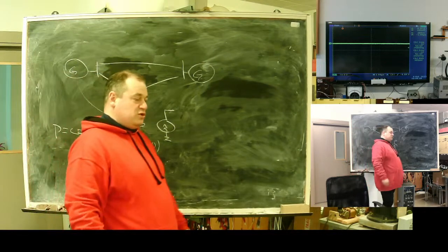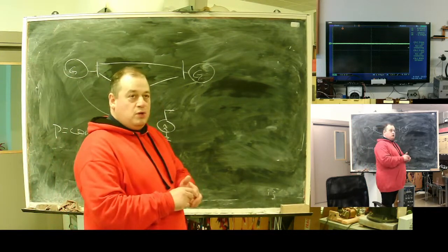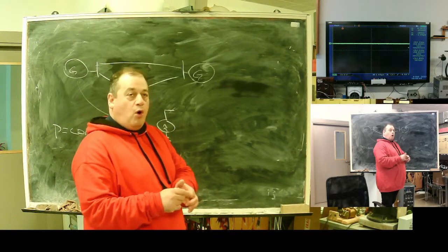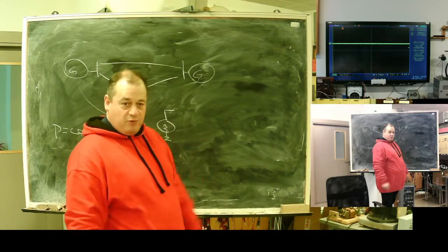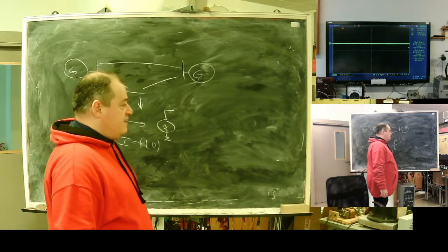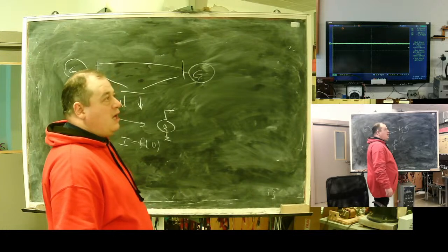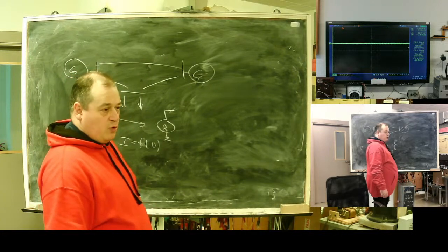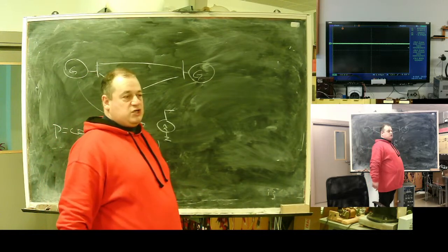In general, there are strategies: PU, keep constant voltage, keep constant power, or simple P, or simple U, voltage. But if there is a network with a huge load, there may be multiple stations controlling voltage, and inner coordination is achieved by droop.